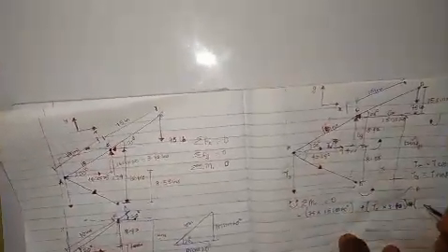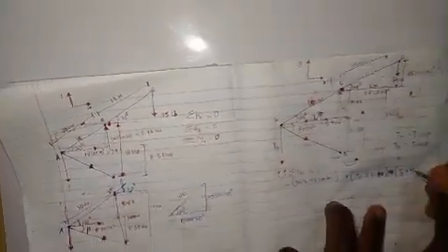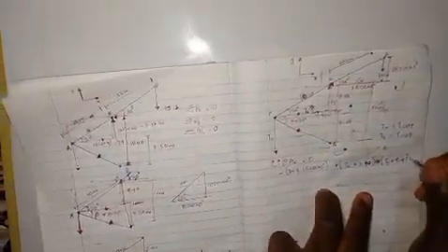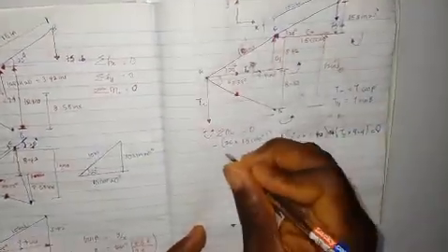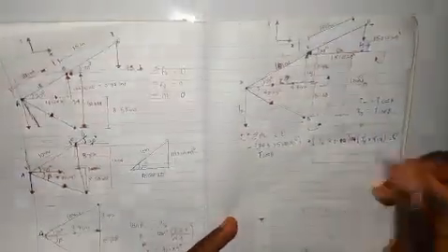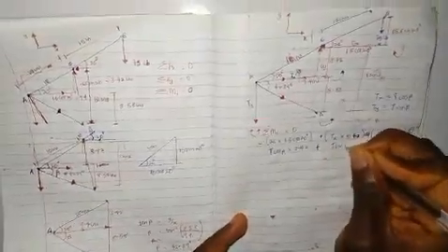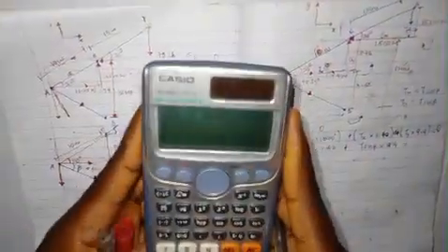This will be Ty times 9.4, which is equals to 0. So from here, don't forget our Tx is T cos beta, then this will be times 3.14 plus T sine beta times 9.4 should be equals to this 15 times cos 20 degrees times